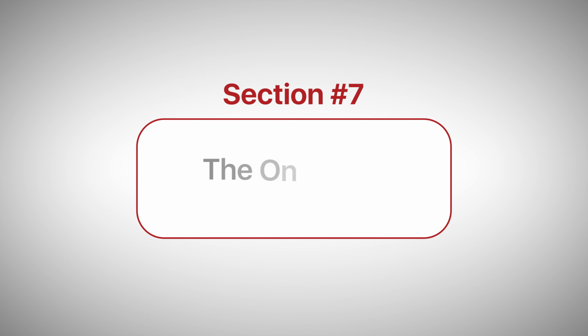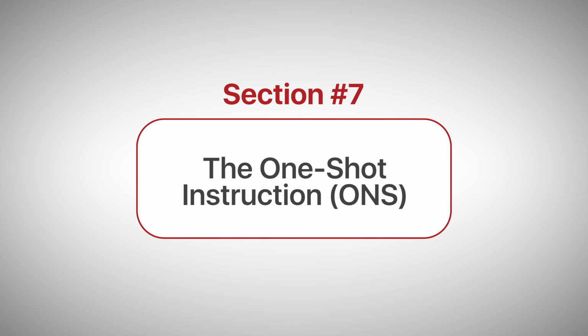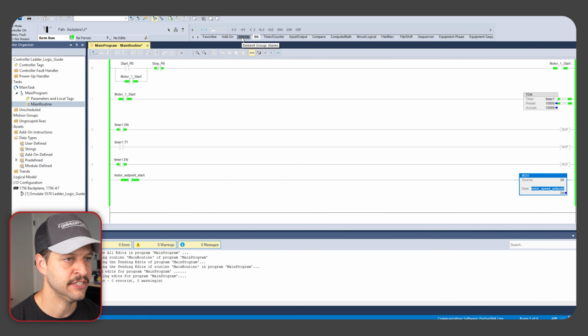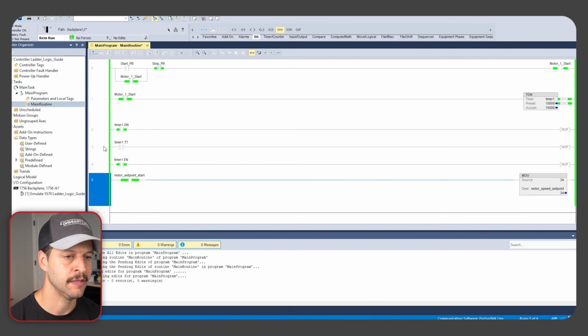Now, one other quick instruction I want to talk about is the one shot. The one shot is a unique instruction that only runs once per scan cycle depending on the input status.